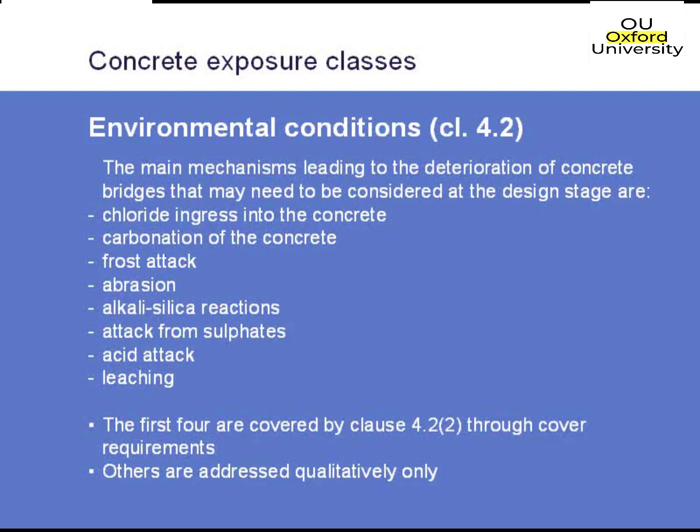The last 4, including the alkali-silica reactions, the sulfate attack, acid attack, and leaching, are not dealt with directly, but they're affected by the type of concrete mix that you choose. So if you've got those sorts of things affecting your concrete, you probably need to be careful with the type of concrete mix that you're selecting to make sure that you get one that suits the environment that you are putting it in.